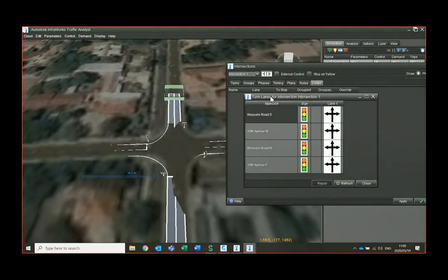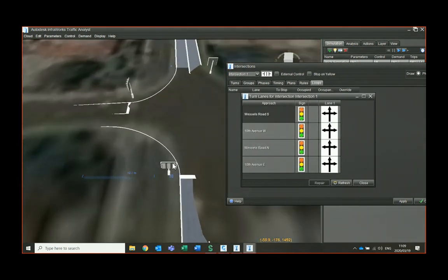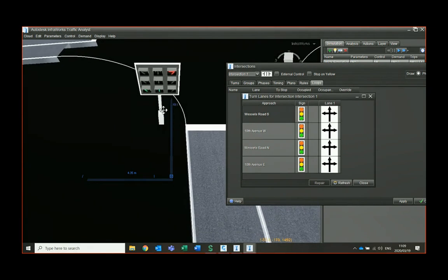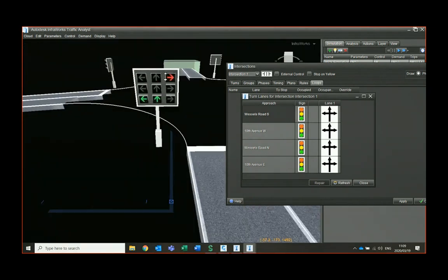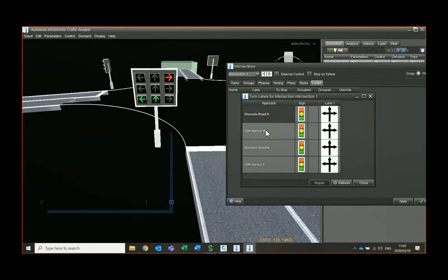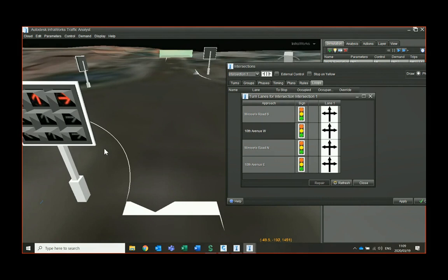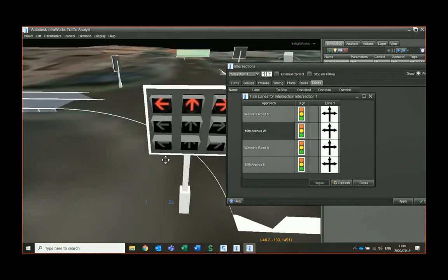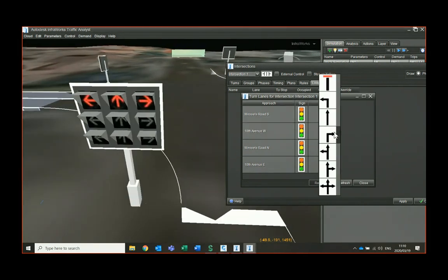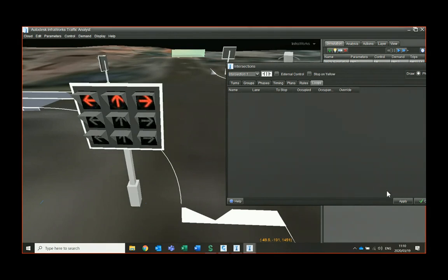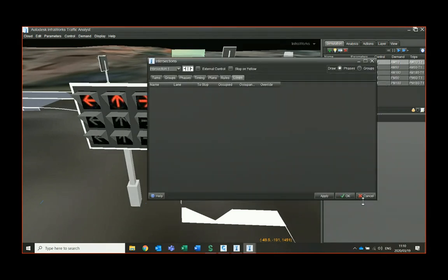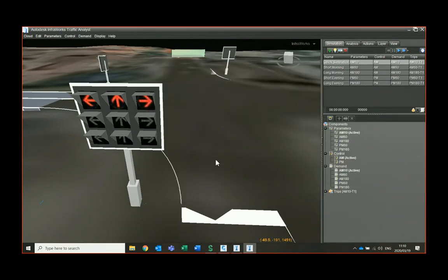You can just give access to a certain lane if it should just be all directions, or if you want to go and define it, you can dictate for that specific lane that it's just a turning lane or it's just a straight lane, or whatever type of setting you want, you can do that. So you've got full control in how to dictate your traffic simulation accordingly to your traffic study.